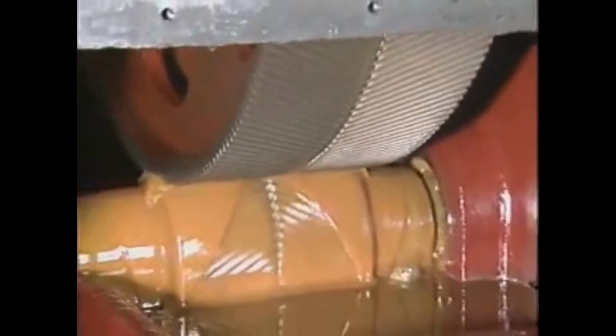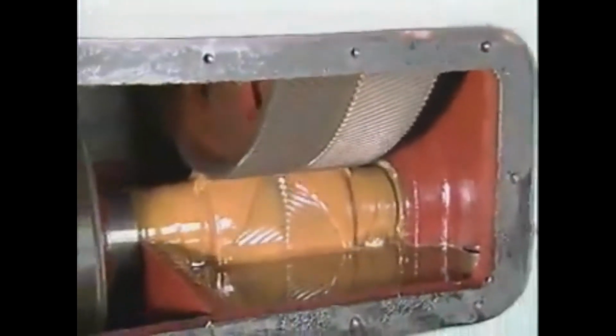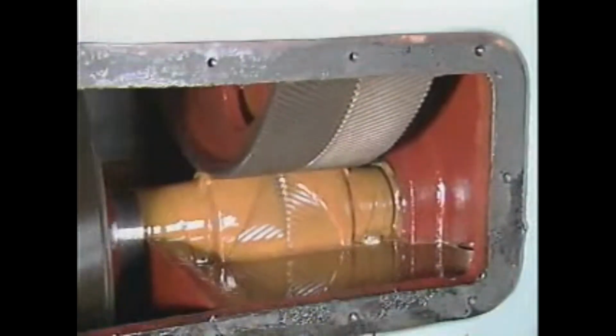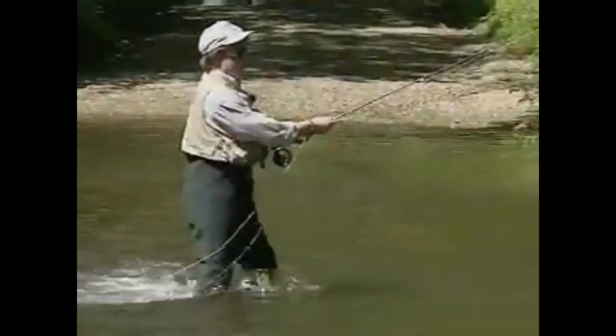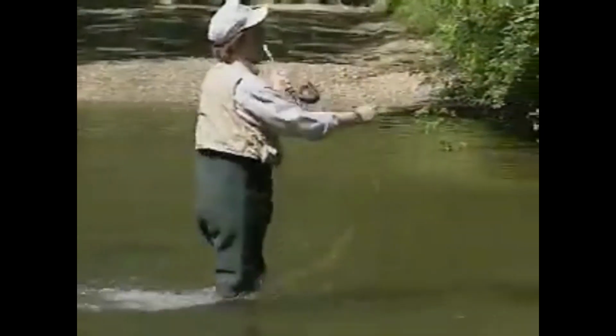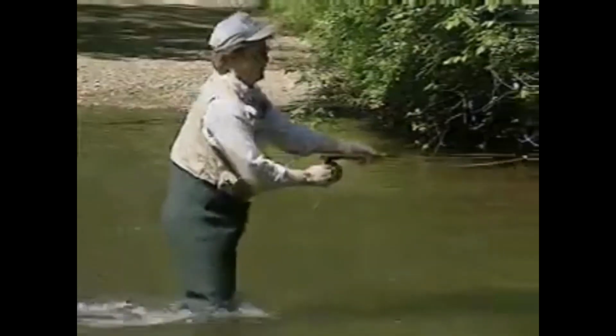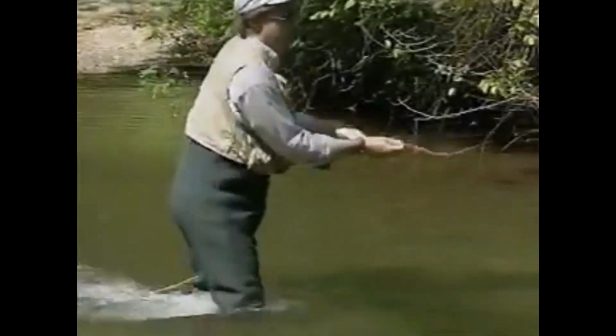Another way to reduce sliding friction is to separate two sliding surfaces with a film of lubricant. As long as the surfaces don't touch, sliding friction is eliminated. Some fluid friction exists within the lubricant, but it's much less than the sliding friction. Fluid friction is the resistance to motion that exists in a fluid. For instance, fluid friction is what makes it difficult to walk rapidly in deep water.